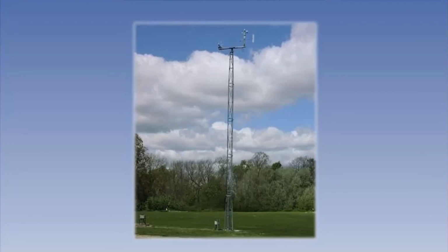These instruments are used around airfields to calculate the approximate surface wind velocity for aircraft either taking off or landing. The definition of the surface wind is one that blows at approximately 10 metres above ground level. The reason for this is that wind velocity changes dramatically with height, and the very near surface velocity can be completely different from that a few metres above the surface. Consequently, these instruments are placed 10 metres above ground level and free of any nearby obstacles that may unduly disturb the flow of air and give misrepresentative readings.